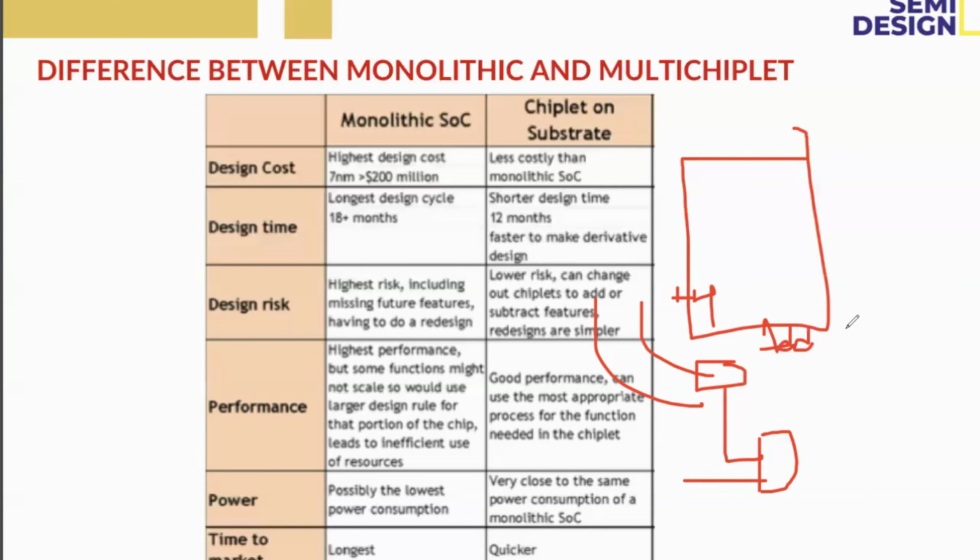Register 1 may have some data like 4C. Add reg 4C comma 2. It will add from the source register and destination register, add the data, and store it in the register. So this instruction will be executed here.